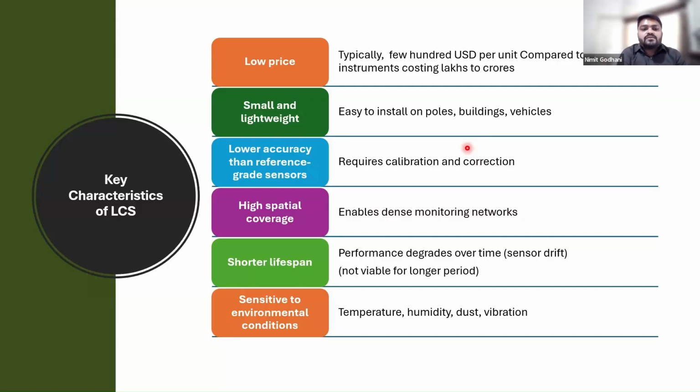There is also a shorter lifespan. Even for most of the sensors you see on the internet nowadays, selling for a few dollars, the data sheet will show that the sensor is capable of monitoring for 5 years, 10 years. Some people are claiming this online for business purposes, but actually it is not true. This needs quite regular calibrations. In our case, we use them in highly polluted areas, and the maximum lifespan is not more than 2 years. We have to replace the sensors every 2 years or so.